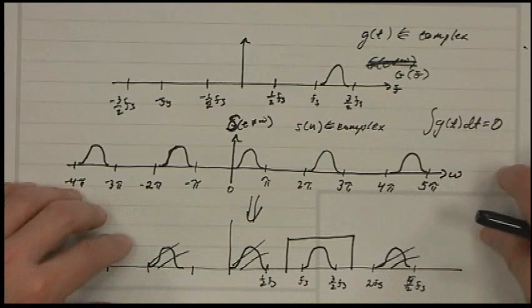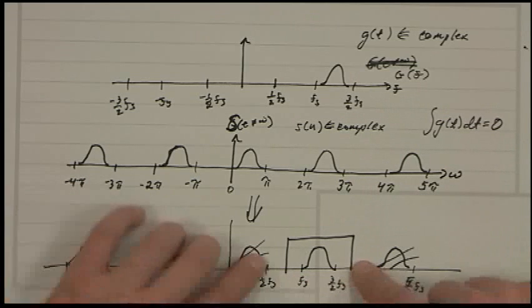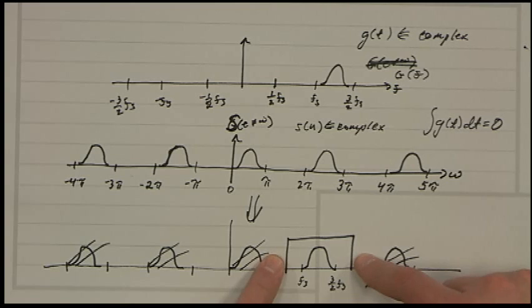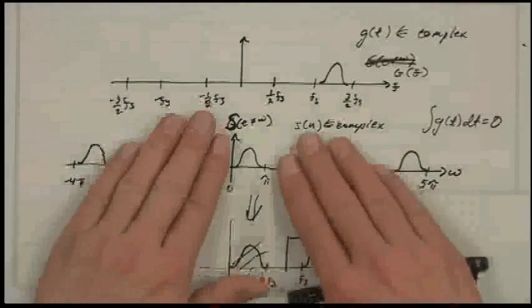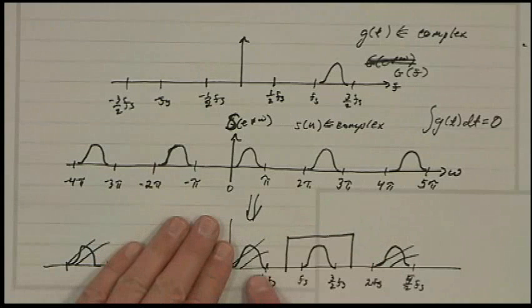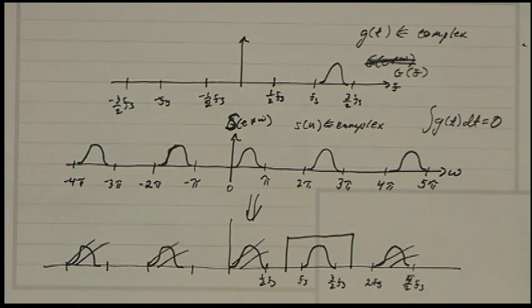Yeah. Professor, how do we apply this filter, which has frequency response beyond Fs? How practically do we do that? Well, this is a high frequency. This is an analog filter, right? So one answer is you design an analog filter with a high center frequency. That could be tricky because it requires that you have a lot of very precise capacitors and inductors and so forth. The other possibility is this: you could pick off this frequency here, and then modulate it up with a mixer. You'll get the same result. That's probably how people would more likely do it.